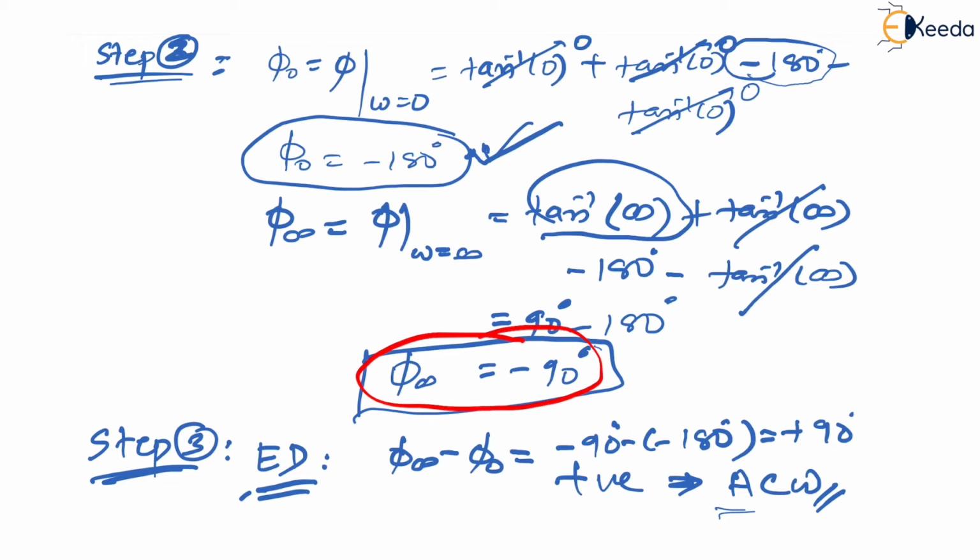When we have the second zero as well, the ending direction angle is equal to minus 90 degrees. Which means that when I add a zero in the system, the ending direction angle is reduced by 90 degrees. You please make a box for it. This is a very important thing. So that is what happens when we have zeros in the system.